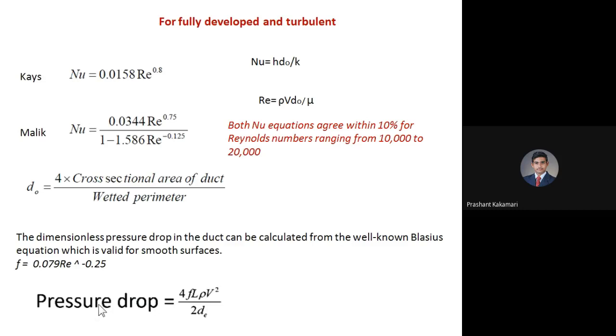And the last part in this topic is using the Nusselt number to find the heat transfer coefficient. Once you know the heat transfer coefficient, or to know the other parameters, you can go for the Nusselt number. Generally we know the Nusselt number is the heat transfer coefficient between the fluid and the surface, h, times the characteristic length, that is L or D naught, divided by K. D naught is taken because if a tube is considered for the liquid flat plate collector, you can take D naught.